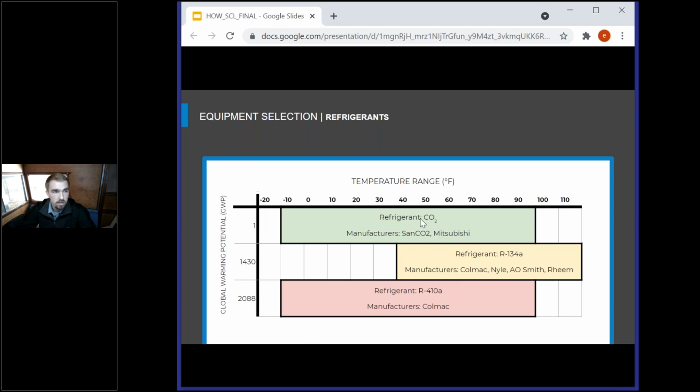So the most fundamental driver of the capabilities of a heat pump water heater is going to be its refrigerant. I talked about how refrigerant pressure is manipulated to be able to transfer heat efficiently into water, but each different refrigerant has different pressure capabilities it can handle and different pressure requirements to transfer that heat. So we can see in this graph here, we have the air temperature it can handle up top here.